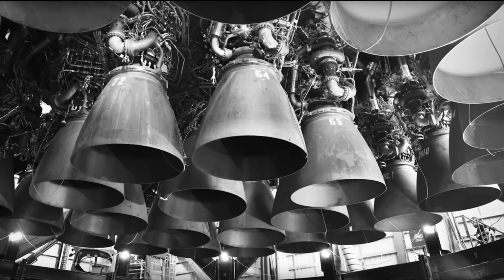Based on the sea-level engines that make up the inner cluster of the Super Heavy's thrust structure, the outer ring is made out of 20 special so-called Raptor Boost engines. The Boost variant is basically the sea-level variant that lacks the ability to gimbal. These engines are not supposed to do anything except generating high thrust numbers, so they don't have to.